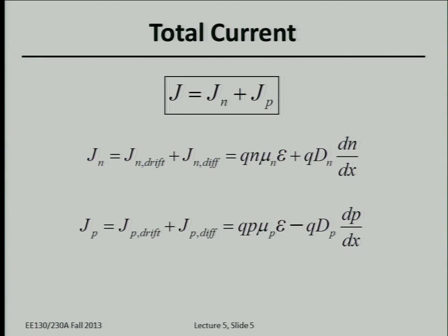So right now, we are able to model, even in first order, the diffusion current involved in the semiconductor. Just keep in mind, those diffusion currents only take place if we have a non-uniform carrier concentration distribution. Also, by combining with the current mechanism we learned in the last lecture, the drift current, I'm going to write the expression here.